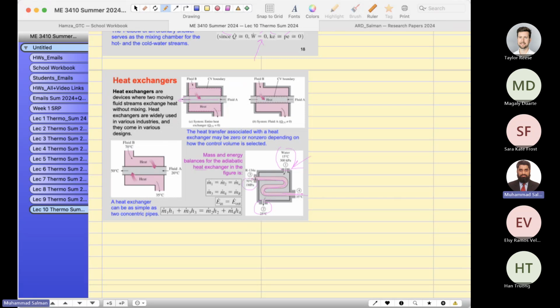Look at here. At the inlet, number 3, the temperature is about 70 Celsius. When it exits, it reduces the temperature. That is the purpose of the radiator: the high temperature water enters the radiator and it leaves the radiator, or heat exchanger, at a low temperature.